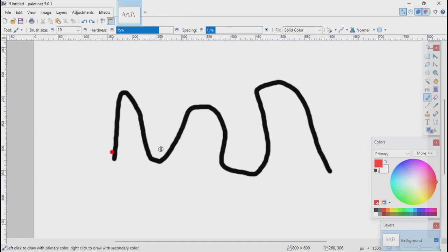What if I only had 2 taps here? I couldn't really draw that. I might come up with something that looked like that, but that wouldn't be right because this has got edges to it, or it's more of a sine wave. So the more taps, the better the resolution. On analog filters, instead of having taps, they would call them poles. The more poles in a filter, the more defined or higher resolution it can be. Same thing here. The more taps, the higher the resolution.